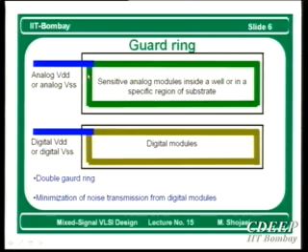So you create a low impedance node everywhere around this area. All these low impedance nodes, which are connected at the end to analog VDD or analog VSS, will dump the switching noise here. Similarly for digital modules.